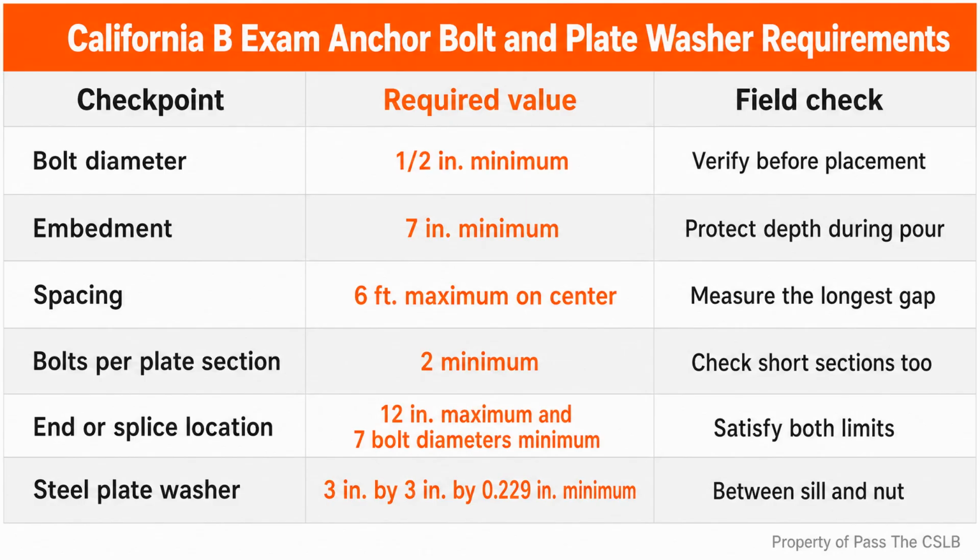Concrete delivery adds a clock to the operation. The report cites the ready-mix concrete limit as 90 minutes or 300 drum revolutions after water is added to the cement and aggregates, whichever comes first. I think of it as 2 clocks running at once. The time clock and the revolution clock do not negotiate with each other.